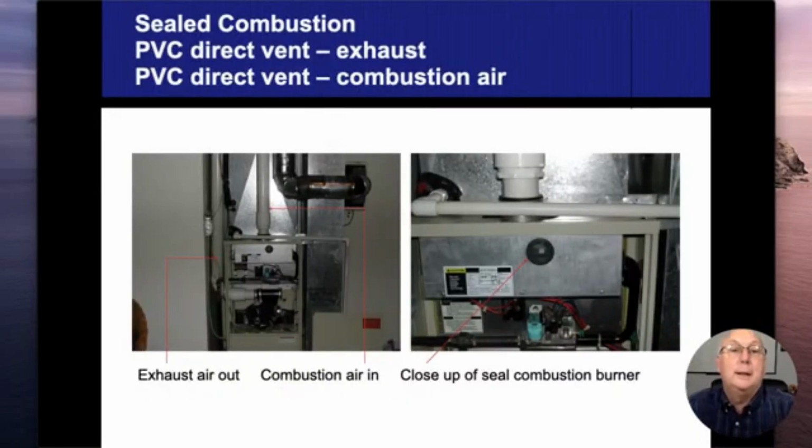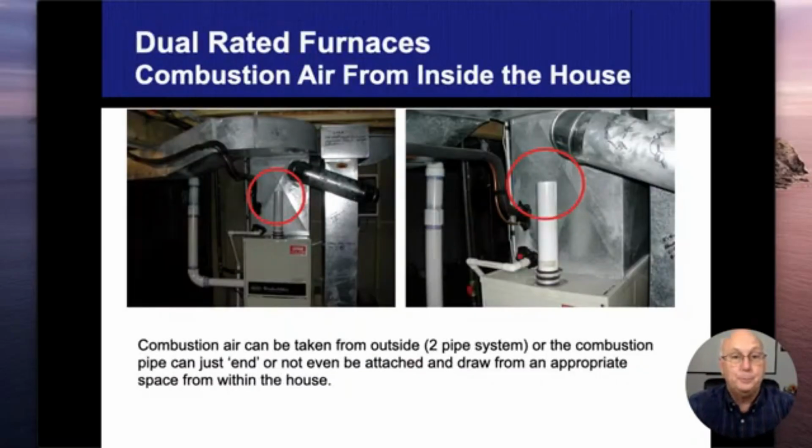Sealed combustion units, we're getting into more of a higher efficiency furnace when we come to it. Sometimes the only thing you can see on the inside of these is through that little peephole right in there, so you're just limited on what you can do. Now these plastic, or the high efficiency units, that sizing of the vent connectors, they can get bigger or smaller. So that sizing to the appliance is only for the mid efficiency furnaces, not necessarily for these. There's not much we can do because they are going to condensate. Liquid is going to come back. They are going to collect it and they are going to drain it. That's what they're for.